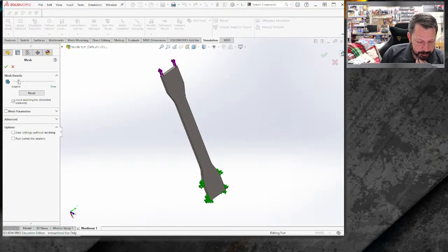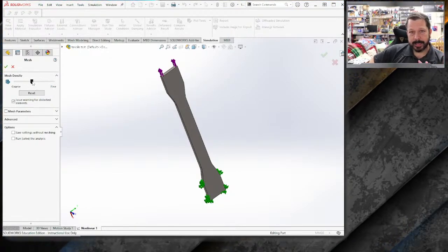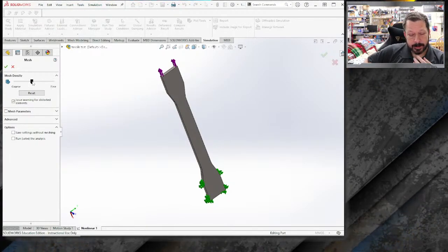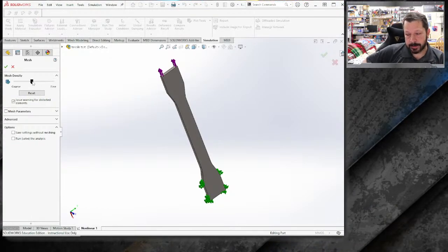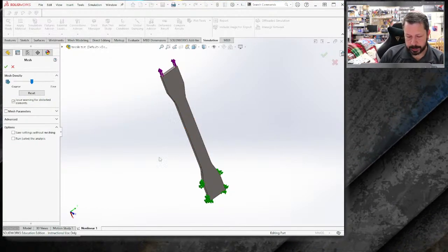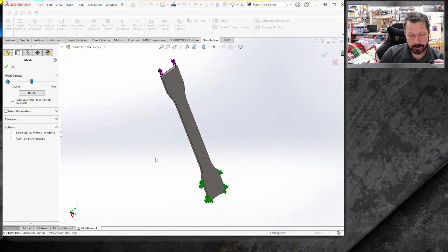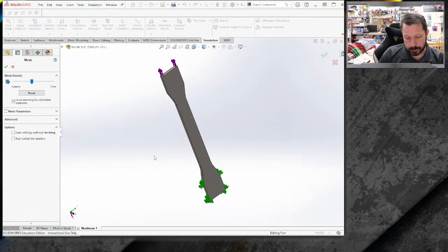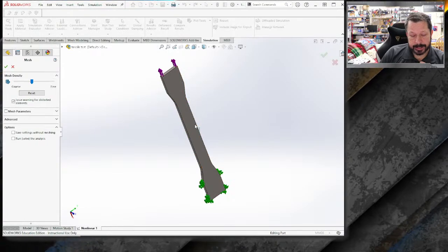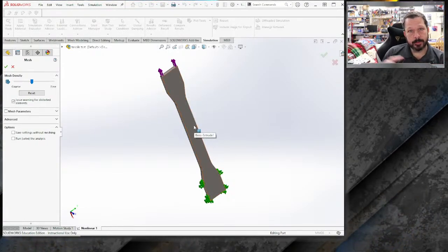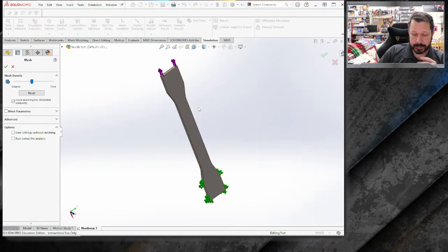So what this mesh density is how this simulation works. It's called finite element analysis, or FEA. The way we've been calculating stresses is, we take this thing, chop it in half, find the internal force, divide by the area, and we know the axial stress. But in the real world, that stress that we calculated is kind of like the average stress. There are stresses much higher than that at different points in the object that's being stressed.